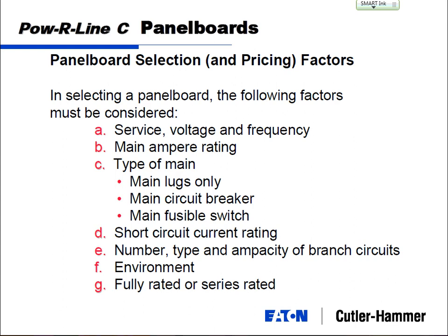Todd, did you see non-metallic panels? Will you be able to have a non-metallic panel? Yes, only on the outside. Let me correct that. Yes, sir, only on the panel board can and the trim. The can itself, the box, the chassis will continue to be metallic. Correct. Do you still have to have a means for grounding? So just the outside, or for grounding the box? You have to have a means for grounding that box for safety still. Is that what they do with it, or just the case?